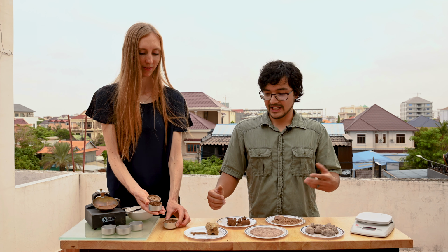Another thing that you'll want to document when you're characterizing coarse-grained material is its gradation. So our two types of soils that we have here represent two different types of gradations that you might characterize for coarse-grained material. The first is what we would call well-graded. Well-graded, as you can see here, has a wide distribution of particle sizes from gravels all the way down to silty material. Well-graded means that there's decent distribution for a lot of particle sizes, especially around the median particle size, which in this case is a coarse particle size.